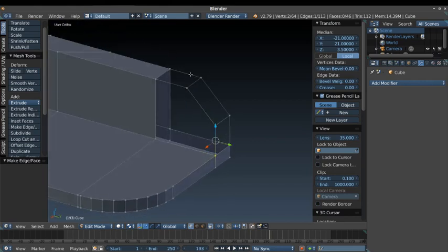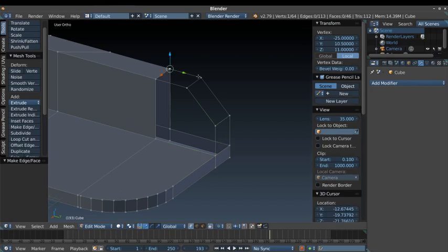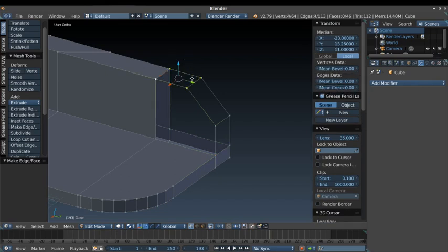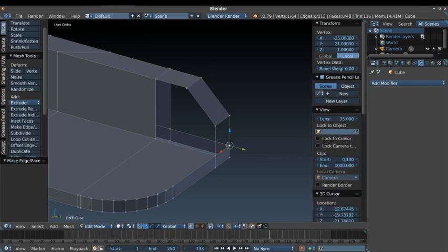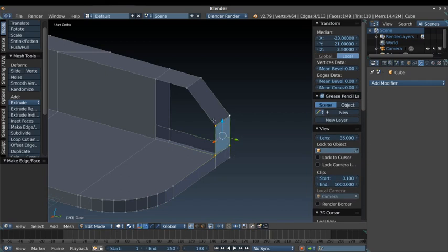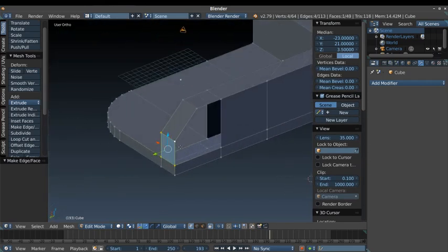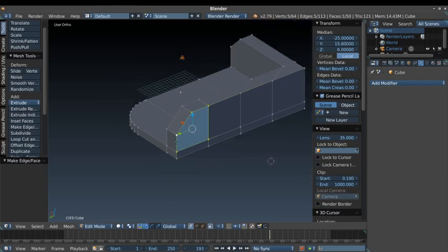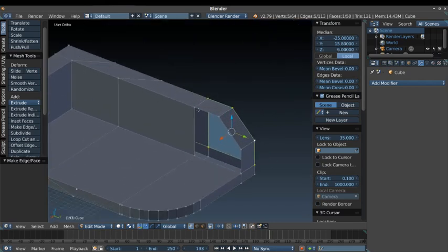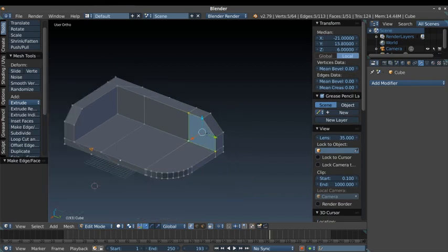And then we can select these 4 vertices, and by typing F, Blender will create a face. This, Shift this, and F, this, F, this, F, and then we select these vertices, this, F, then rotate the view, and this, and F, and it's done.